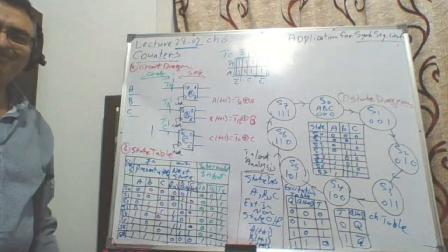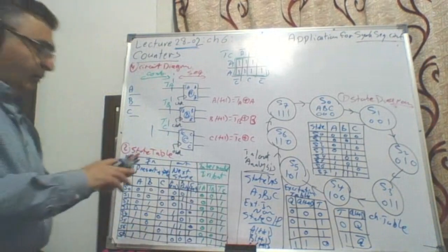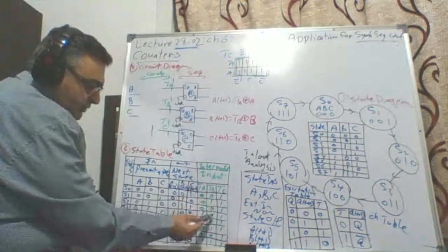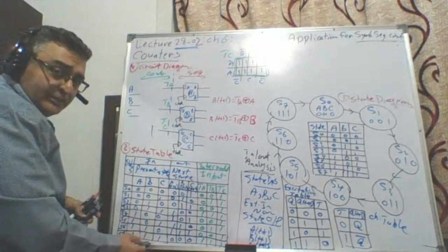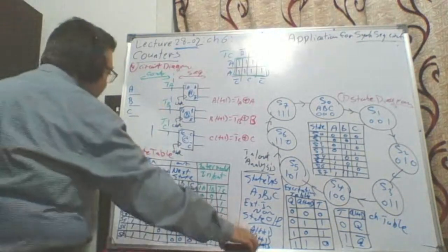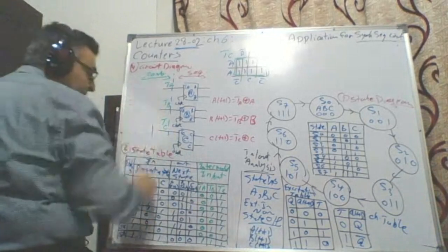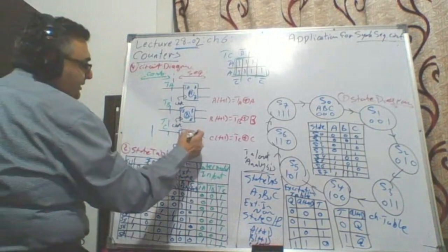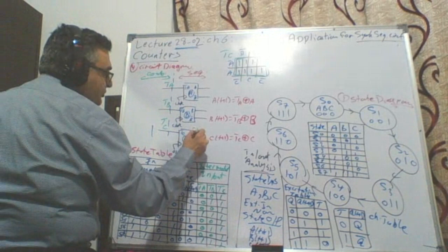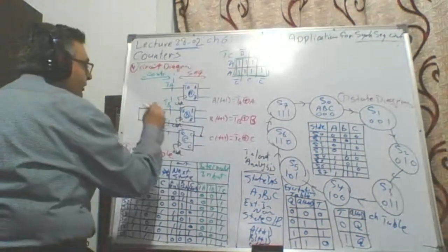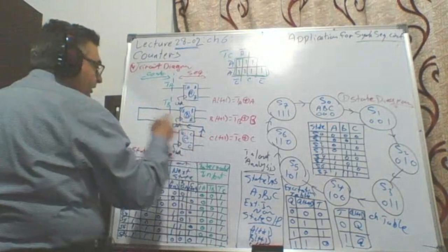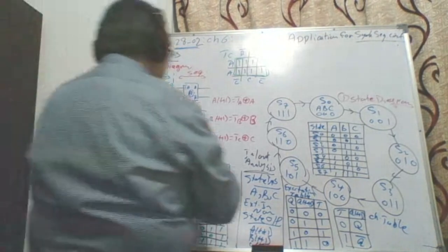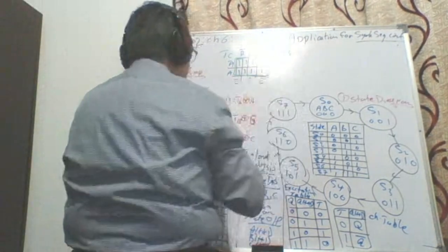That's it. Agree? Now I will go to TB. Can you get TB? TB is 01010101. Can you see it? So TB is also very simple to design. All I have to do is connect the input C. I can take the input C from here and connect it in feedback to TB. You don't believe me? Let's design TB. TB, K-map.